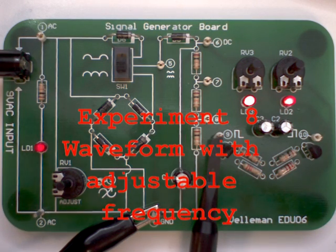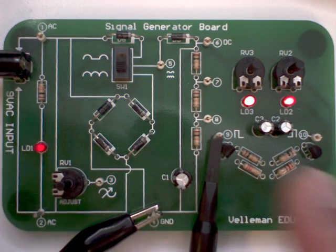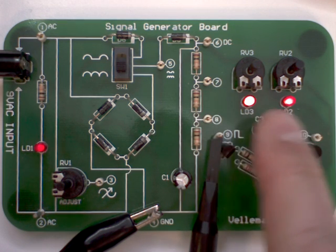Welcome to Experiment 8, Waveform with adjustable frequency. Connect the alligator clip to the ground of the board and connect the probe tip to the oscillator output, that is test pin 9.